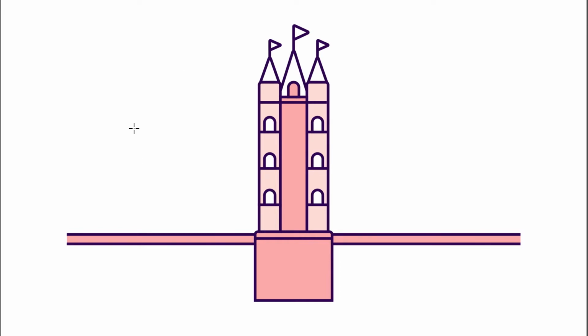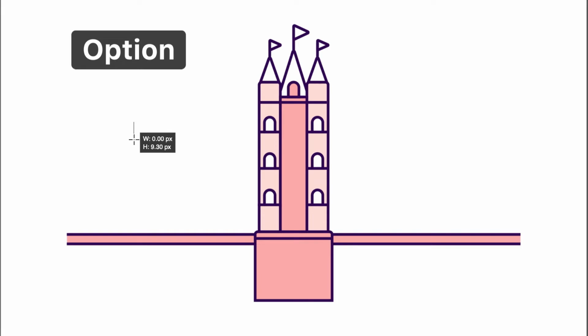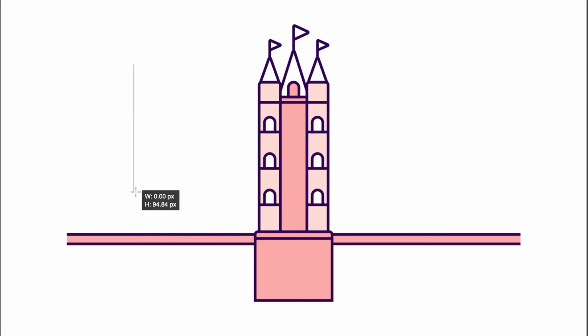Please note that if you hold the Option button while drawing the line, the first click will define the center of the line. The position of the cursor will define the length and direction of one shoulder. Another shoulder will be of the same length in the opposite direction.